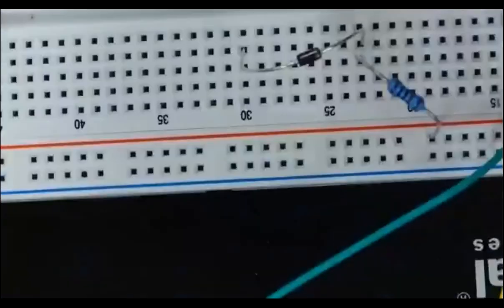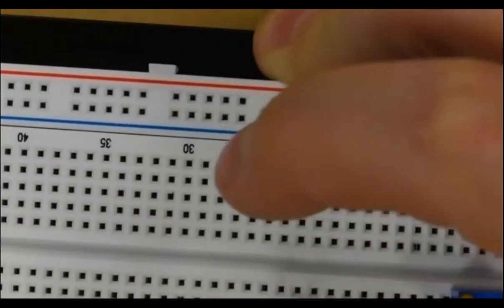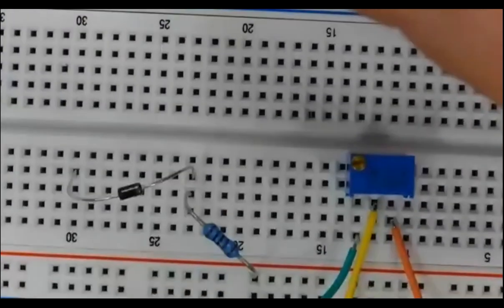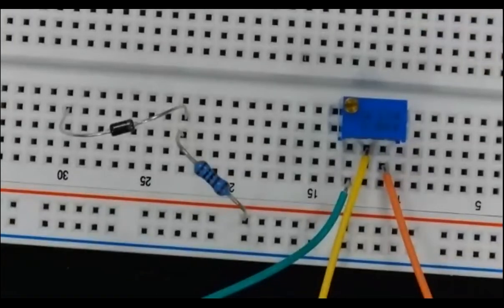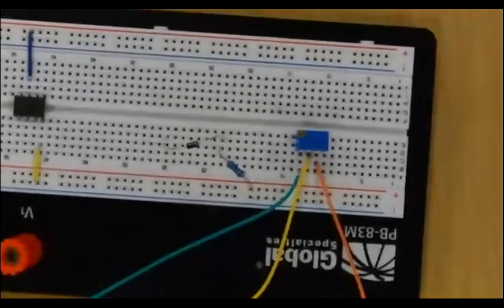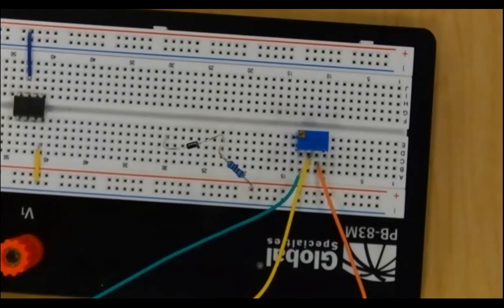The reason that we have unpredictable behavior is because there's no input that tells the signal what to do. It's not really hooked up to a particular voltage or anything. It's sort of like if I hold a wire up in the air and I ask you what voltage that is, well, what does that mean?